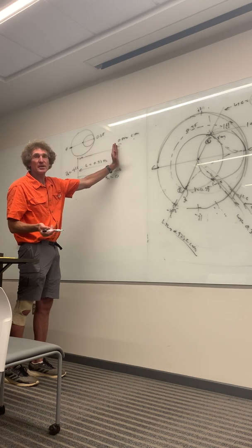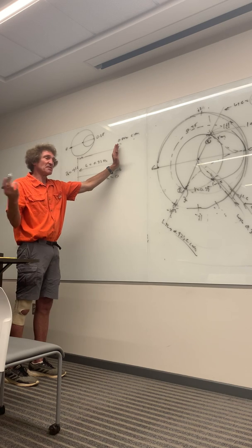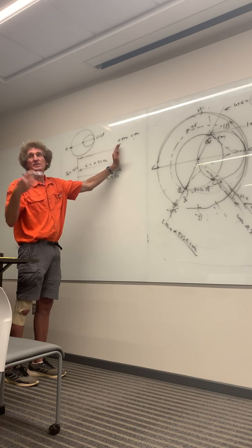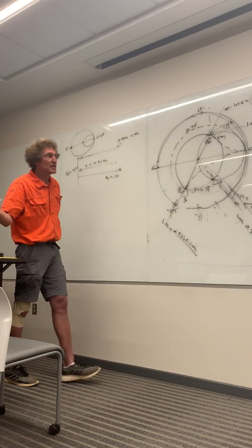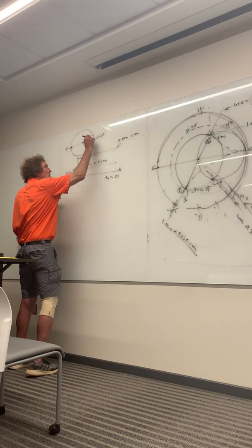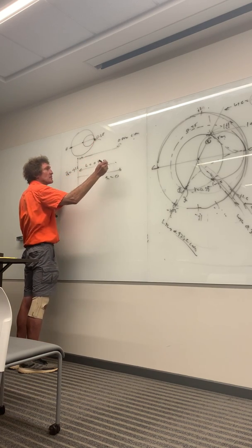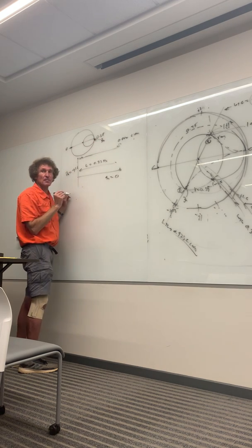If it is an open circuit here, well, what's the impedance of an open circuit? Infinite. It's infinite, right? When normalized, it's infinite. Infinity divided by anything finite is still infinite. So that means when you come into your Smith chart, you come in over here. All right, if this transmission line is an open circuit, this would be your Z load right there.